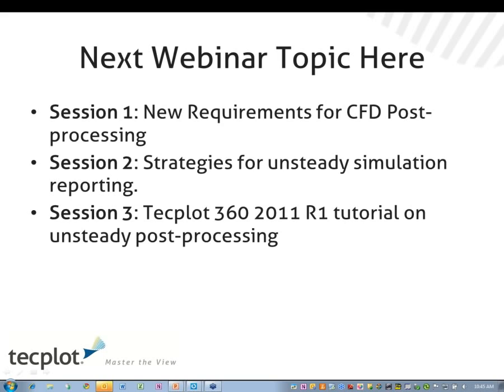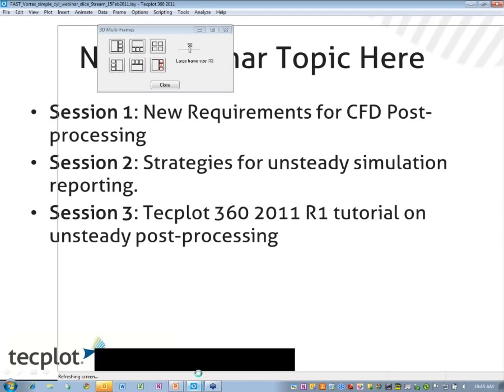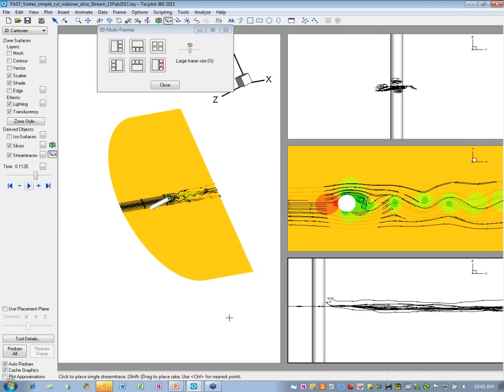There was a question about the accuracy of the calculation scheme on vorticity. It's slightly different with ordered and unstructured grids. With ordered grids, it is second order accurate center differencing for the velocities. And with unstructured, it uses a moving least squares scheme.